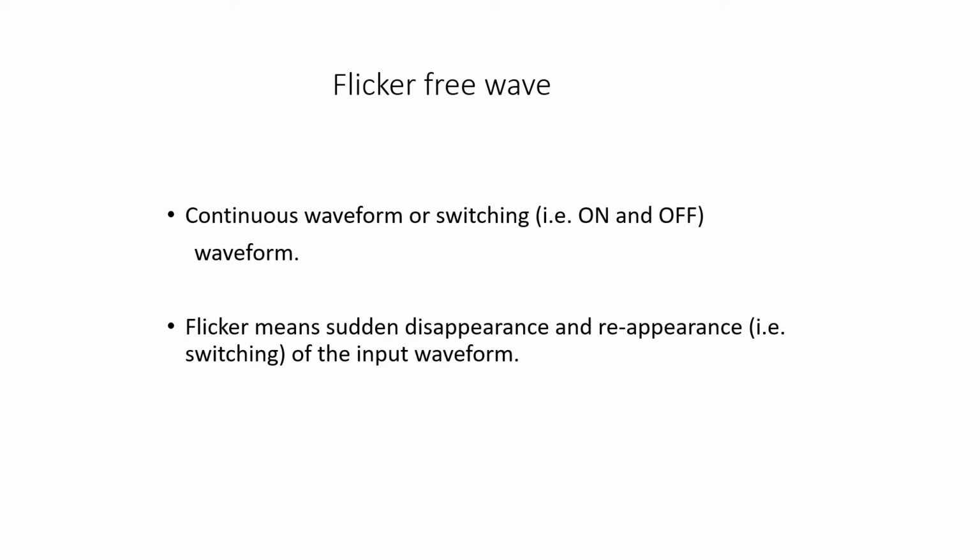When the waveform moves left to right, the internal sweep frequency is less than the vertical signal frequency. When the waveform moves right to left, the internal sweep frequency is greater than the vertical signal frequency. In either case, stationary waveforms are obtained by varying the variable sweep control. This control sets the sweep signal frequency to integer multiples of the vertical signal.